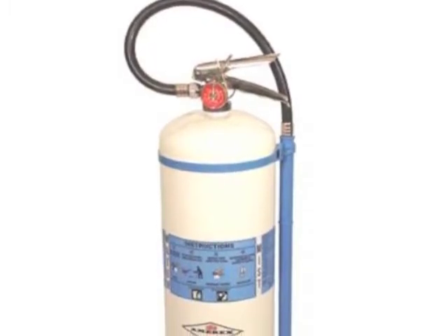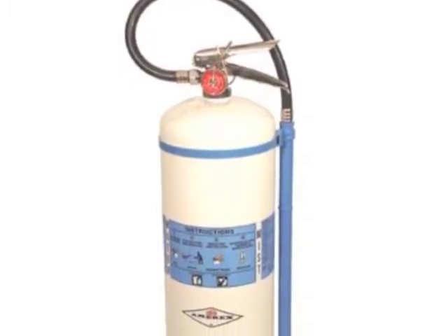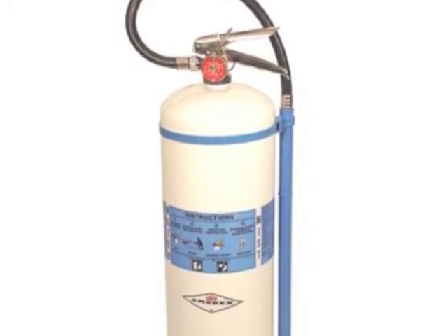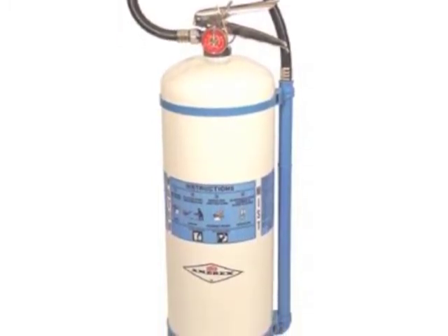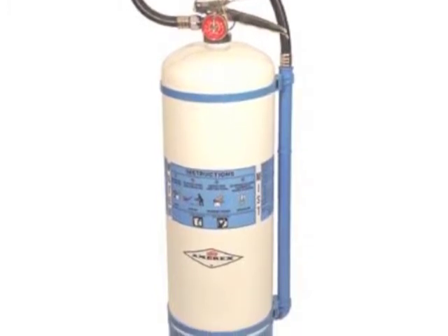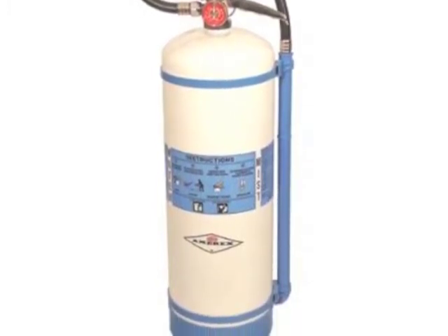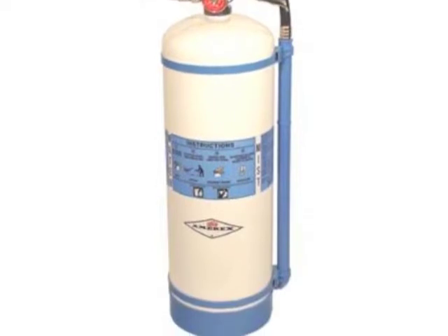Water mist extinguishers are a recent development that extinguish the fire by taking away the heat element of the fire triangle. They are an alternative to the clean agent extinguisher where contamination is concerned. Water mist extinguishers are primarily for Class A fires only, although they are safe to be used on Class C fires as well.